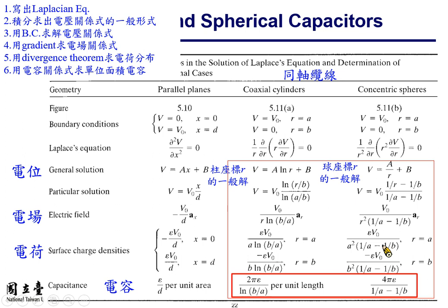So here is the B over A ratio. So if you want to increase the capacitance of your coaxial cylindrical structure, the B over A ratio should be smaller. So that means the values of A and B should be closer. The B over A ratio should be as close to 1 as possible.